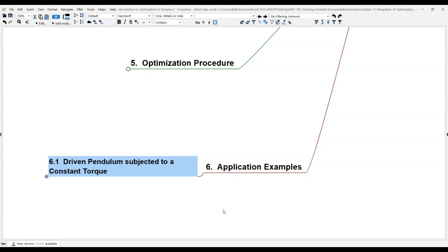Let's say, for example, we go to speed. What will happen? So instead of having a 4-dimensional problem, you're just going to have a 3-dimensional problem. Under your inforces.m file, you're just going to change the torque back to, let's say, 10 Newton meters or whatever value you want to use over there, and then make sure that you have 3 variables at the end.